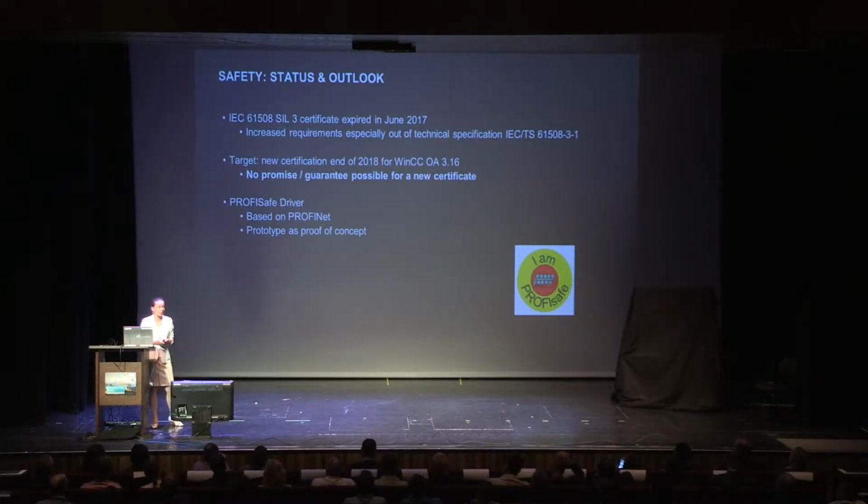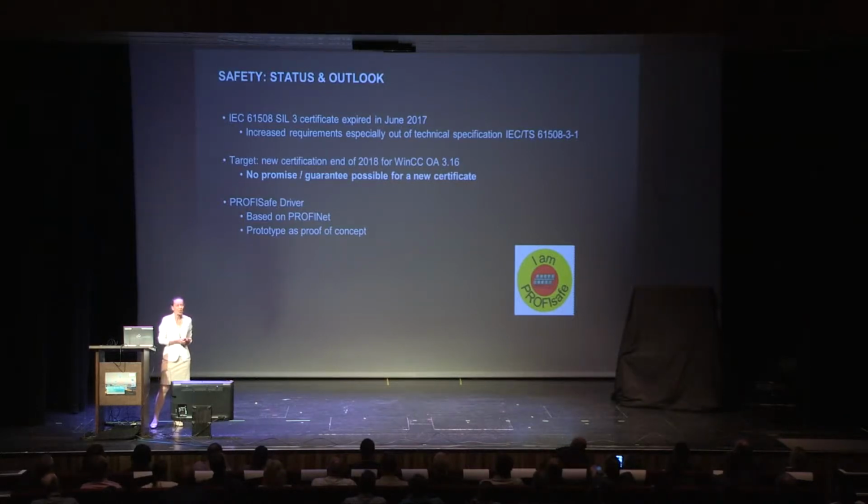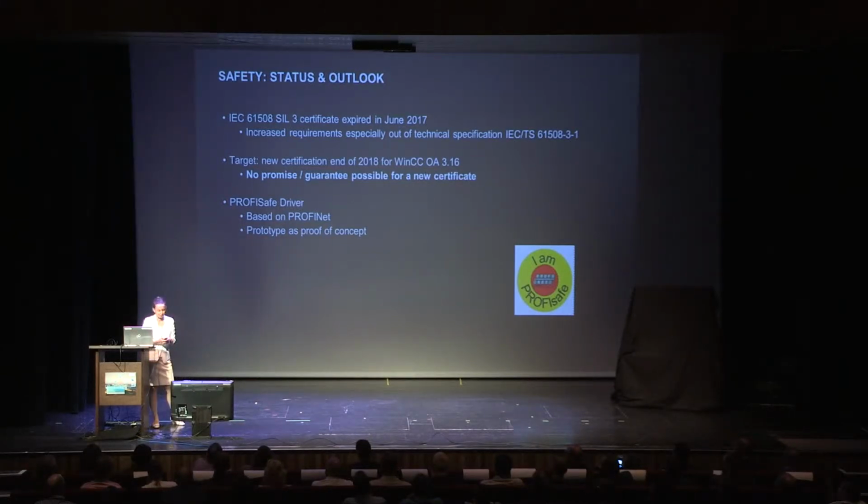We were also looking at PROFIsafe, which is a technology for safe communication according to IEC 61508. And we developed a prototype PROFIsafe driver based on PROFINET. And we will discuss the findings of this prototype with our certification body and then finalize this, so there will be a PROFIsafe and PROFINET driver available within WinCC. This finally closes the safe communication gap between the end of a WinCC driver on the one hand side and the PLC at the other side.